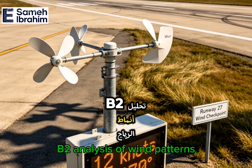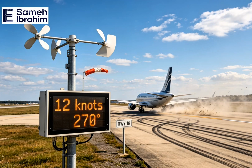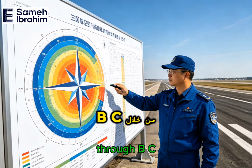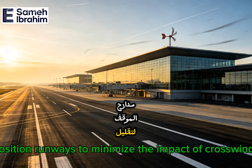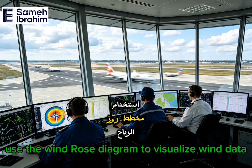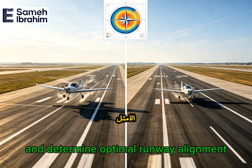B2. Analysis of wind patterns. Identify prevailing winds, most frequent direction and speed. Assess crosswinds and tailwinds that could affect takeoff and landing. B3. Runway orientation. Position runways to minimize the impact of crosswinds and maximize headwinds during takeoff and landing. Use the wind rose diagram to visualize wind data and determine optimal runway alignment.